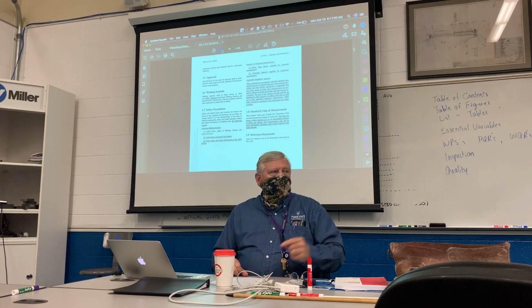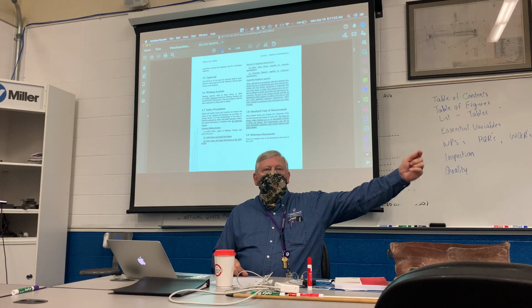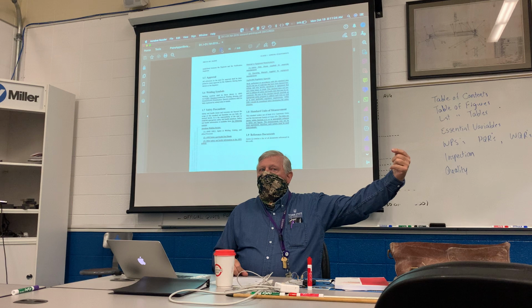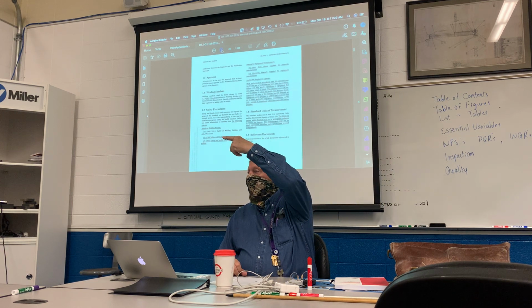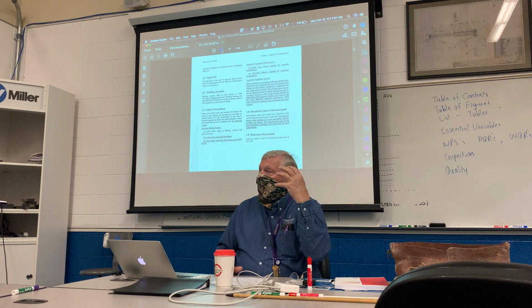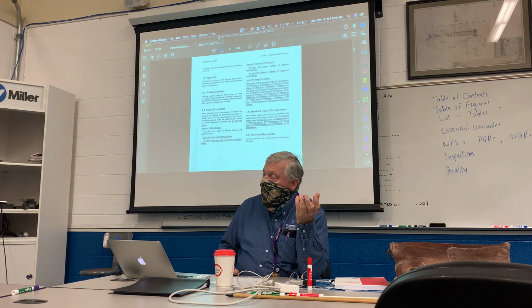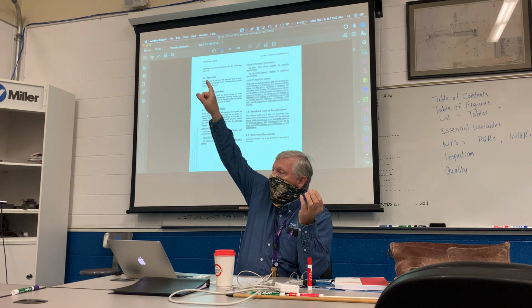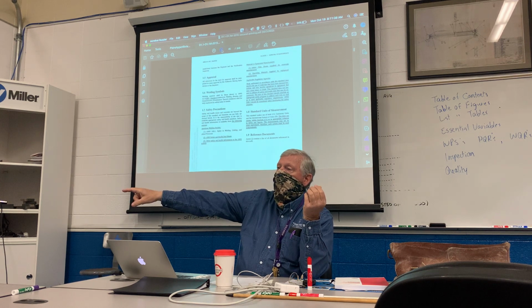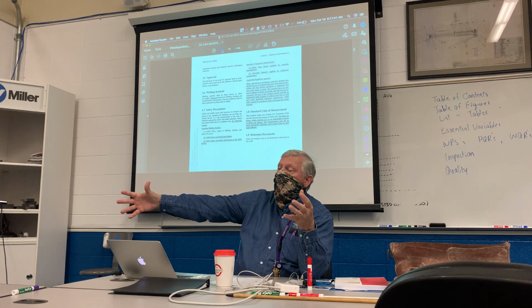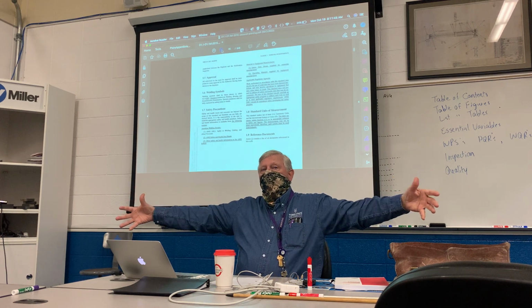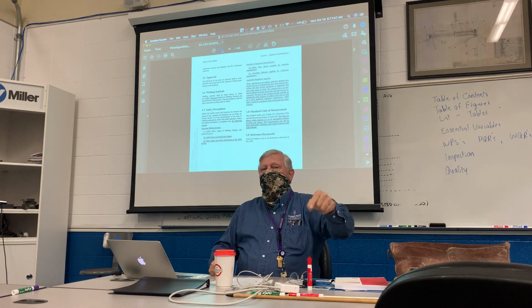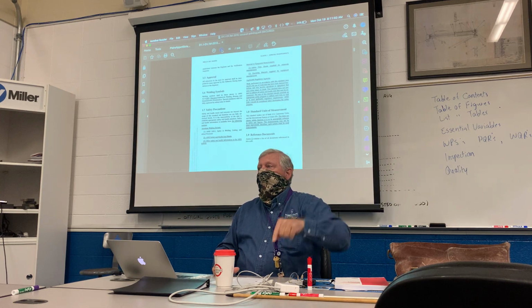Okay. So we start off over here. We come up off of the pump, and we put the pipe at grade exactly like he's drawn it. You're trying to point out a 1/2 inch per foot of grade is going to have this pipe going through the roof by the time it's on that side of the room. You try to tell them that, and you get demanded in front of other people. You build it just exactly like I drew it. I don't want to hear from you again.